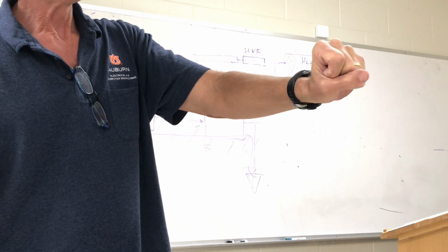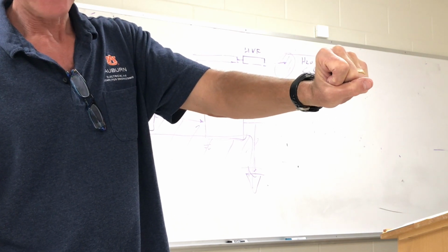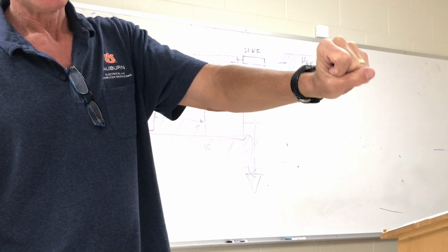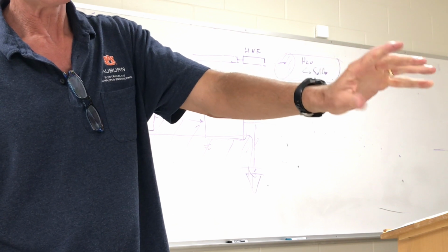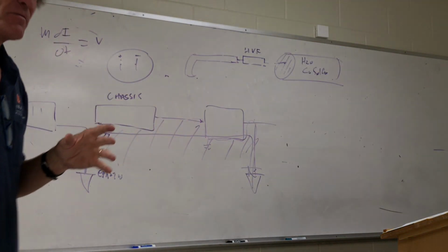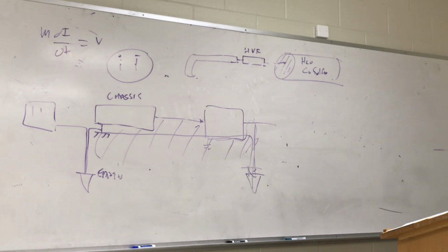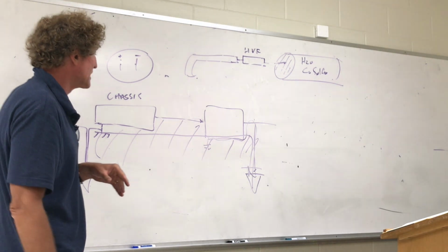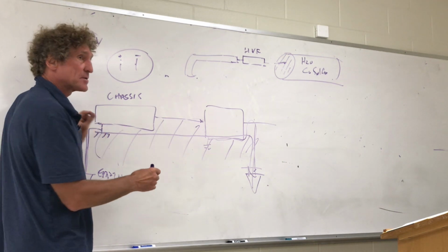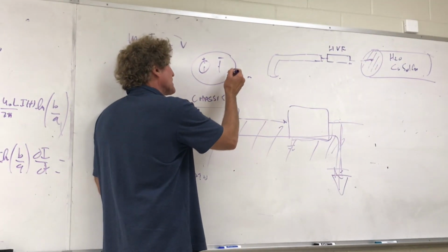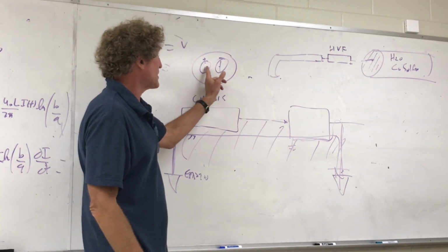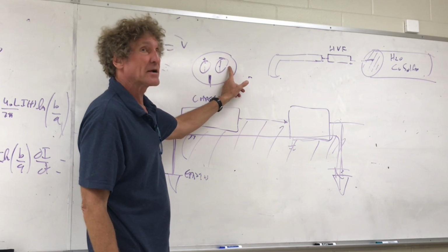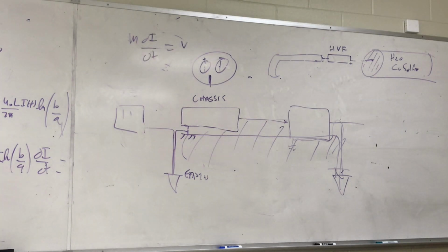Typically, no, but you get a heck of a whack. If you're standing in a salt water solution and you grab it with a very salty hand, you might get knocked out and die. But that would be for a 240, I mean, when you get plus or minus 120, it'd be hard to do that, but it's possible at least. So what they do is they have a ground fault indicator. And if the current going through here is not the same as the current in there, it trips. So there's a ground here. The minute this current is not equal to that current in magnitude, the breaker trips. That's the ground fault breaker. And that's the thing you should be thankful for.